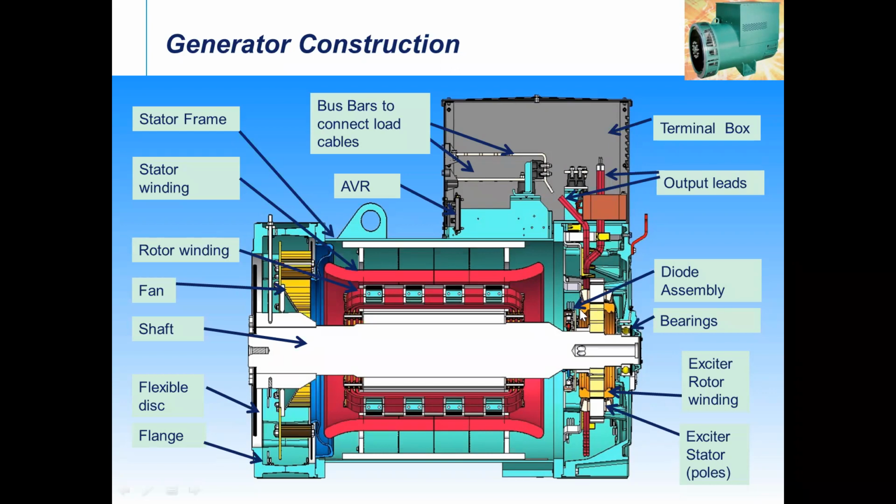And we will be talking about the rotor assembly, where there is a diode, a rotating rectifier assembly, the ND bearing, the exciter rotor winding, and the exciter stator, which we'll talk about further in our slides.